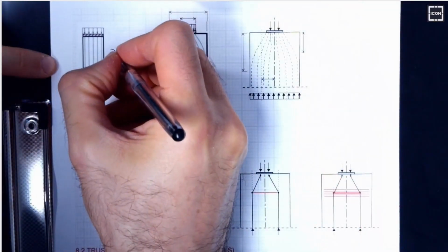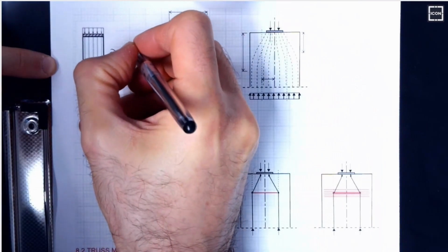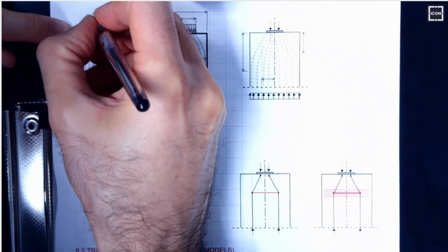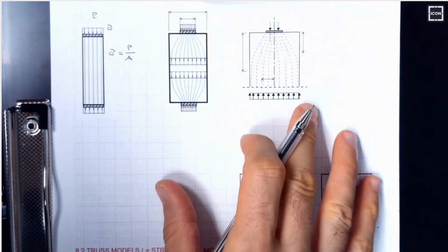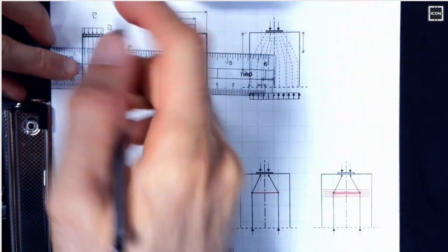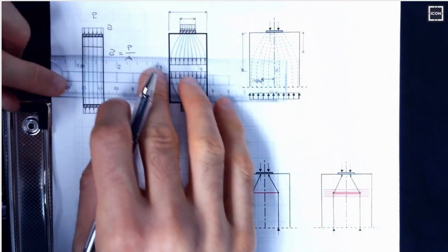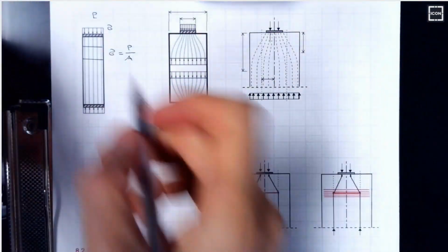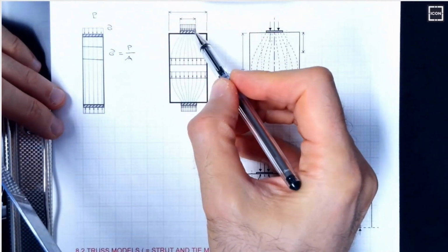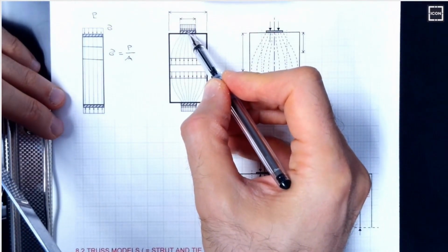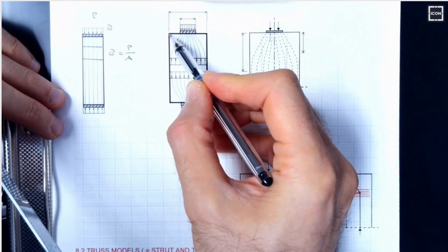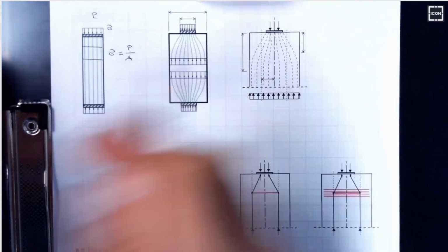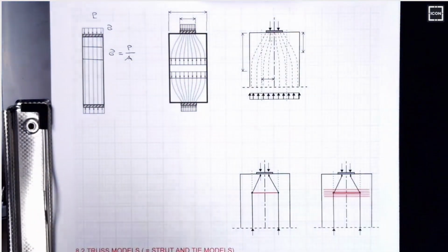A stress distribution sigma would be equal to P divided by area, right? So let's say he's applying force P and this is stress sigma, and that would be the case everywhere, right? So it would be a constant. It's going to be here, same stress. It's going to be here, it's the same stress. So it would have been the same stress everywhere on this section. But if you have a difference between the load application area and the sectional dimensions, there is going to be some stress flow. There is going to be a disturbance, right, for this situation.